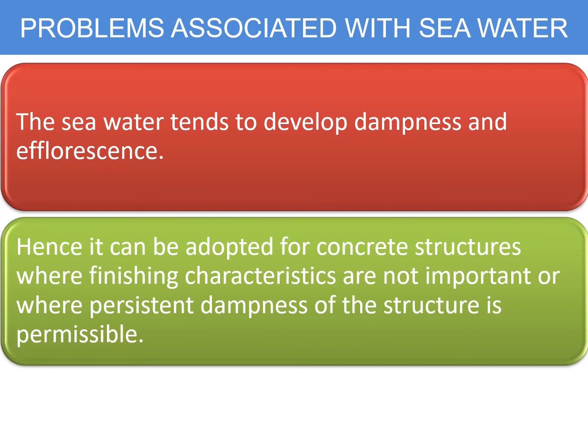But ideally, if it is SRC and compressive strength is the only criterion for approving concrete from the durability point of view, then probably with SRC you can go for curing of concrete with seawater. But when flexural strength plays a major role in the design of the elements of the structure made of concrete, then probably you should not go for curing of concrete with seawater, because flexural strengths are reduced drastically, to the tune of say 40 to 50%, when seawater is used to cure the concrete.